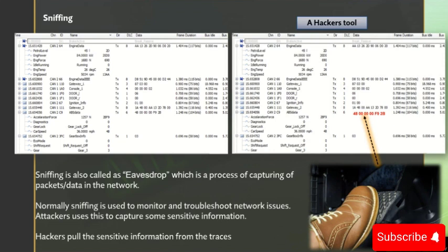But if he wants to understand what is the signal for the brake pedal, he can simply make some actions on the vehicle just by pressing the brake pedal, and the message corresponding to the values will be highlighted, so that he will come to know, by playing certain actions, what are all the CAN messages that are giving the flow.